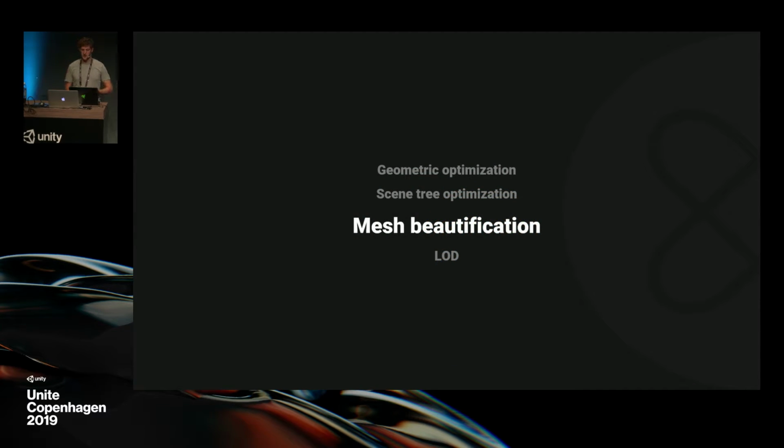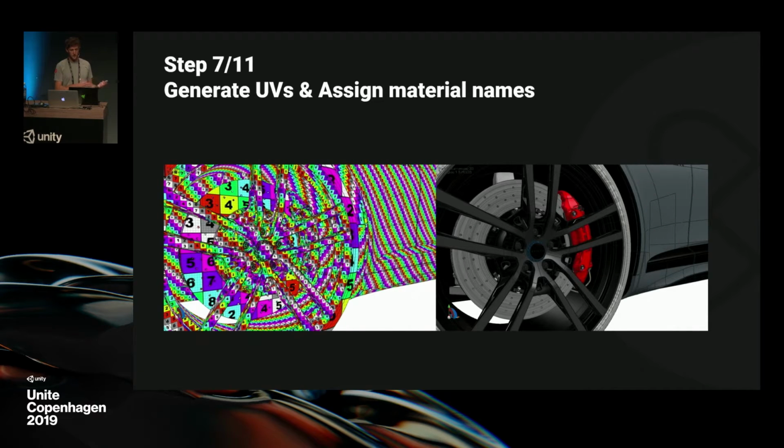Now, third step is mesh purification. It's the process required for the meshes to look beautiful and realistic in Unity. So I mean with nice shaders and textures later. Well, in our case here, there are almost no materials nor UV information in our CAD file. So first, during this step, we generate basic UVs by simple box projection on channel 0 on the full car.